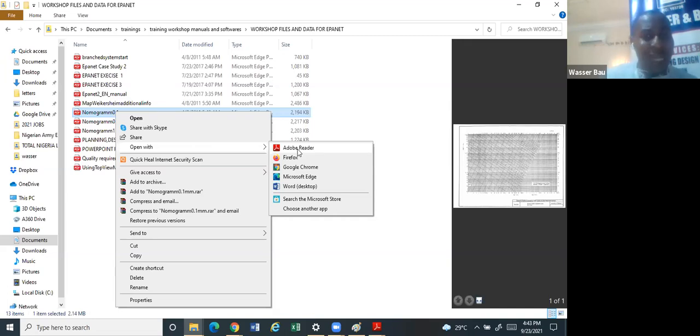For instance, for the pressure standard, if your pressure is more than 8, you have to zone them. If you don't zone them, the material we have in the market, some of them cannot take more than 8 bars. So that means there's going to be pipe burst. Even if you are going to buy new pipes, there are modern pipes now that are up to 12 and 16 bars. But we know that the average pipe in the market, as at 2-3 years ago, is about 8 bars. And even if you can buy a higher-rated pipe, how about the appurtenances? How about the other components of the network? Can they sustain any pressure that is more than 8 bars? So that is why you do that.